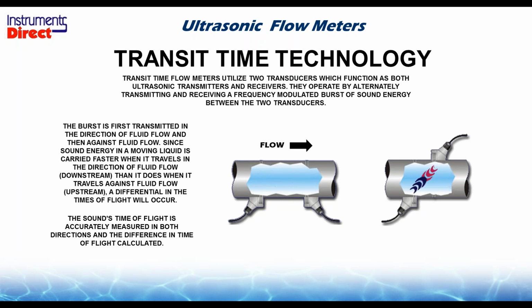Transit time will work on ultra pure liquid applications like deionized water, jet fuel, well water, drinking water, sewage, but it doesn't do a very good job on sludge. So transit times traditionally work on ultra pure liquids up to about 2% suspended solids, which is now in your sludge and oatmeal category. So transit time will do sewage. The Doppler will usually do sewage unless it's all clean liquid, or you have some turbulence or aeration from a pump.